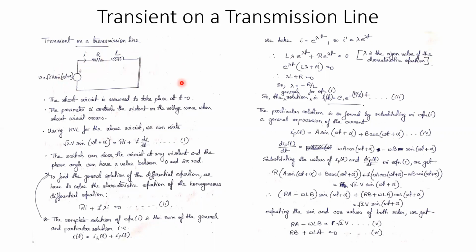The load has obviously been neglected, as it was told earlier, that in case of a fault, the current flowing into the fault is so much that the current drawn by the load is negligible. As the fault point voltage is very low, the current drawn by the load from the fault point voltage is also very low. So the load current is negligible compared to the fault current. Most of the current will flow into the fault.